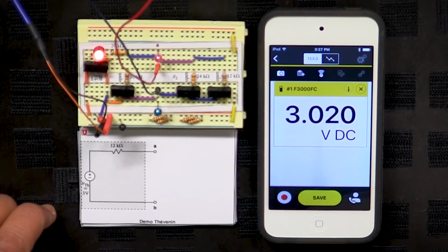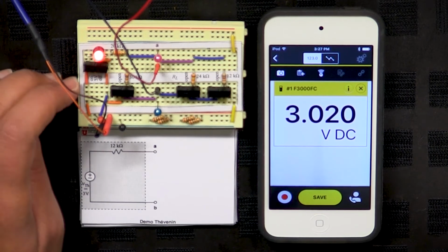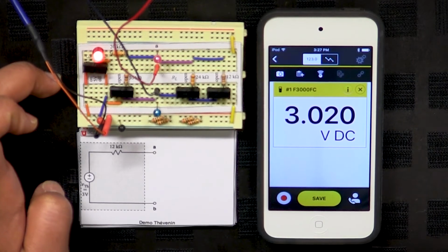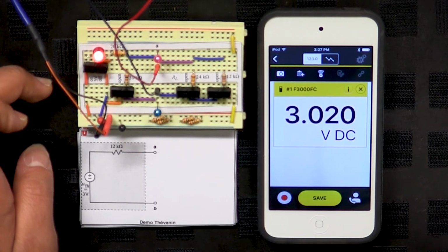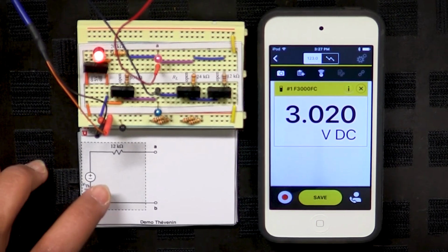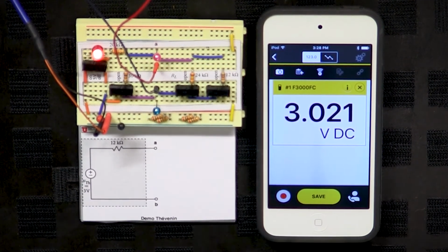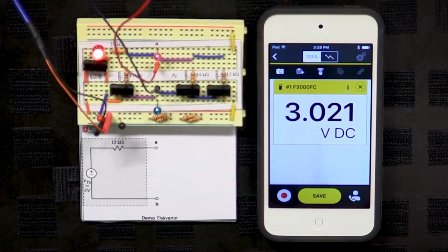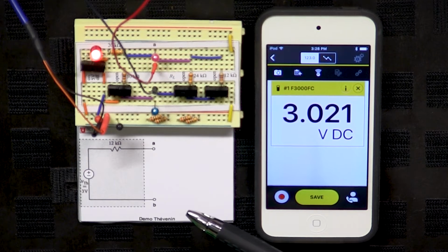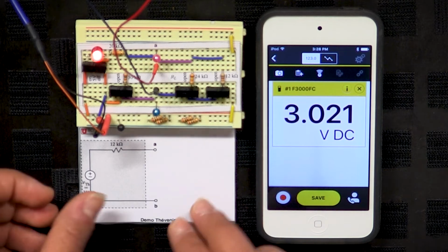Okay, now this shows that in the circuit that we just showed you with a 5 volt power supply, a 20k and a 30k, the Thévenin equivalent circuit consists of a 3 volt voltage source in series with a 12k ohm resistor. Now let's add some loads to port A and B and see if the original circuit measurements agree with what we calculate in the schematic that has the Thévenin equivalence in it.